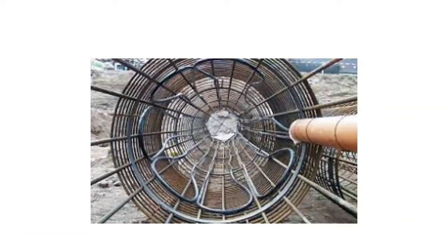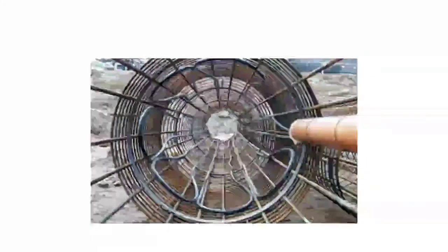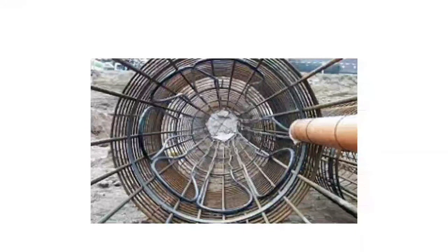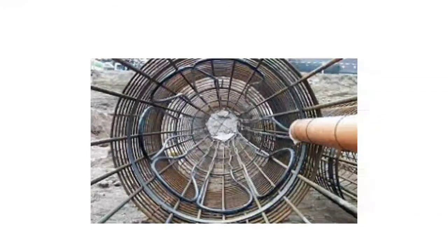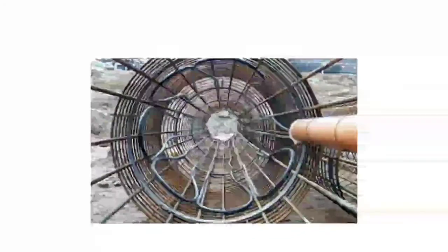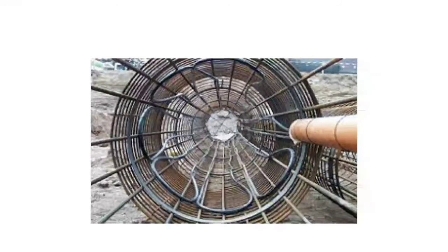When you're constructing it, once you have attached the pipes to the reinforcement cage, this cage will be lowered carefully into the borehole, into the hole. Once it is placed inside the hole, the pipes will be filled with water. If this locality is an area where the temperature goes below freezing, then it will be filled with saline solution.